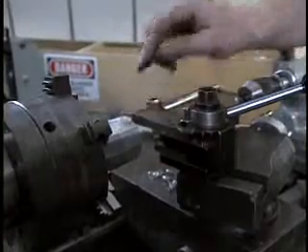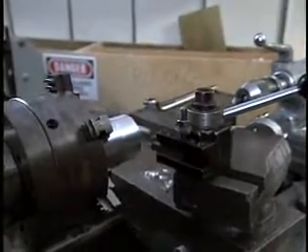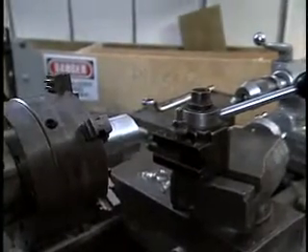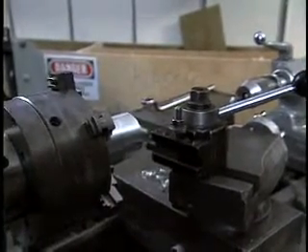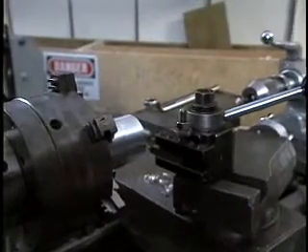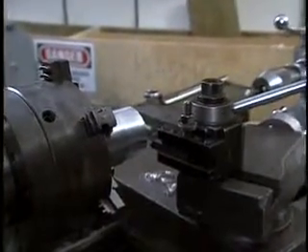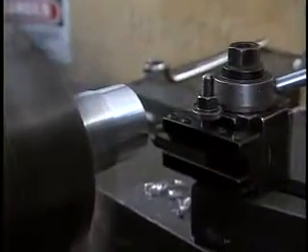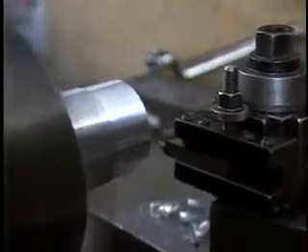Now I've made one roughing cut, and the finish is reasonably good, but there are grooves remaining in the part because I was feeding by hand and was not able to control the speed very accurately. Now I'll take a finishing pass on this part, just a few thousandths of an inch. I'll take 5 thousandths of an inch on this pass, and I will use the power feed.